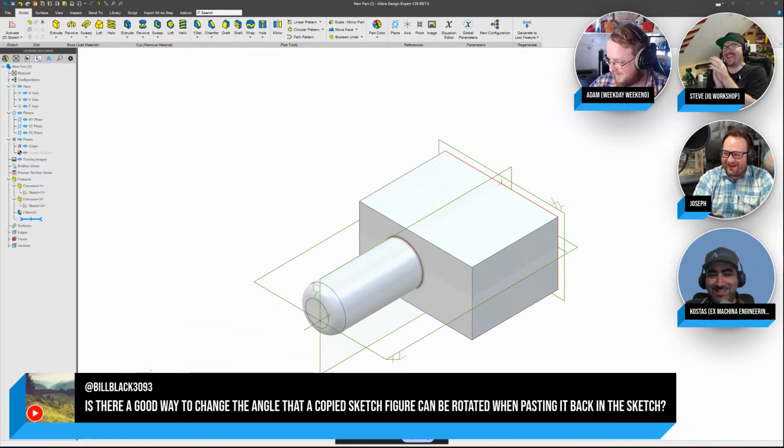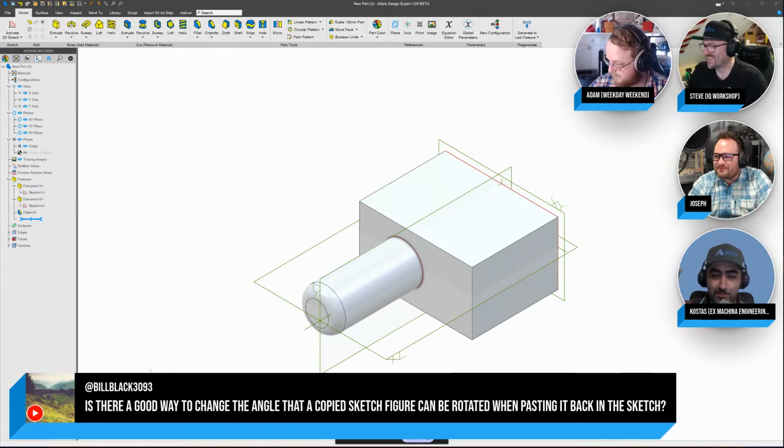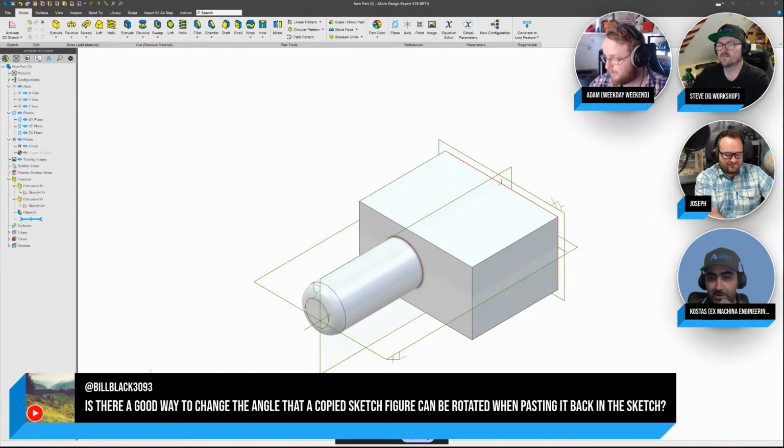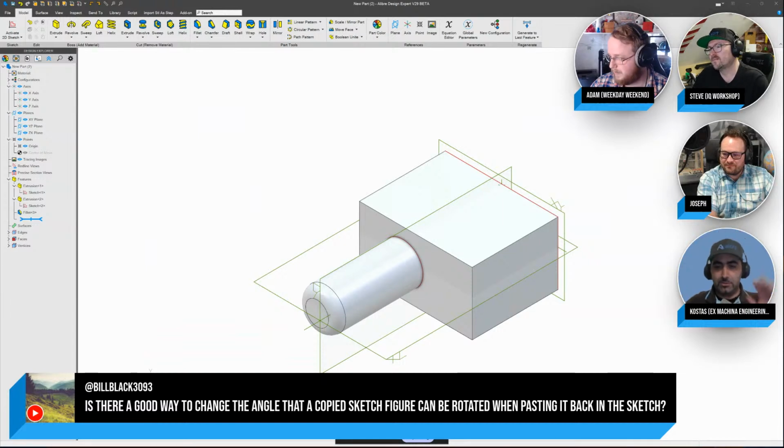After that, you need to know that when you're using the paste stamper, when you copy with a base point, then you can use a paste stamper. And when you stamp what you copied, you also stamp the constraints and dimensions. So if you have an angle dimension there, you can stamp it, and then you can change those. For example, you're copying a square and you're picking up the dimensions as well, and you stamp it, and then you can change those dimensions and make a different square. That's a really powerful use of the paste stamper, right? And you can do all sorts of stuff with that. Very nice.